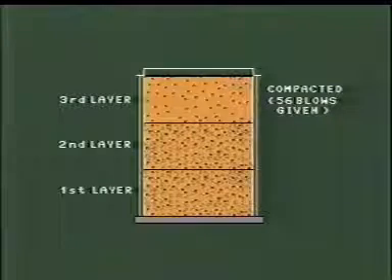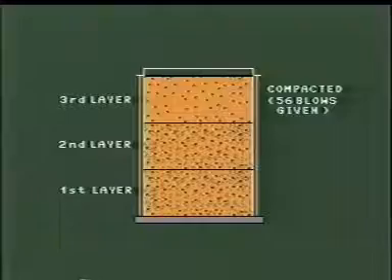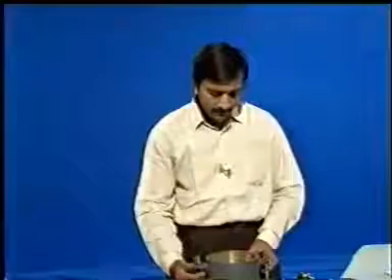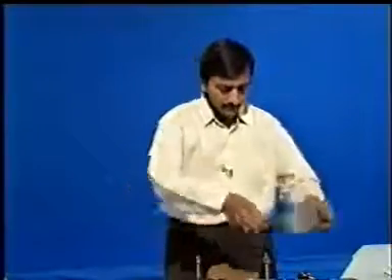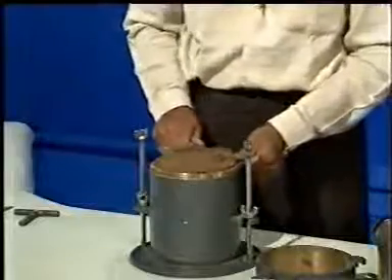After compacting the top layer, remove the collar and trim off the top surface.